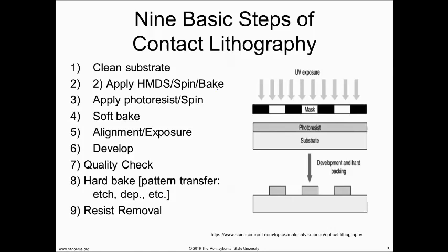And I'll give you this right now as a hint. The resist is, we talked about, an organic polymer. So you guys should know from your chemistry, organic polymers are carbon and hydrogen generally, right? And then other things. But their backbone is a C and H kind of deal. Does that make sense? So my question to you, a rhetorical question, is, how do I get rid of these C's and H's, my photoresist that's left in step number 9? My photoresist is made out of carbon and hydrogen.